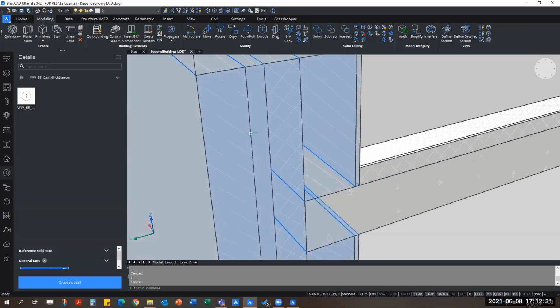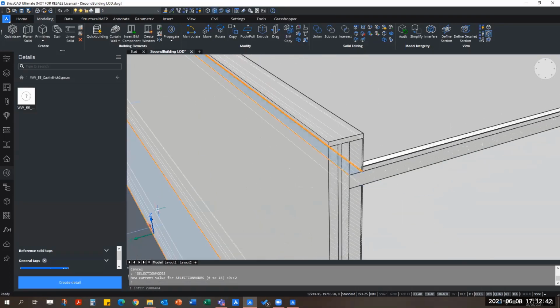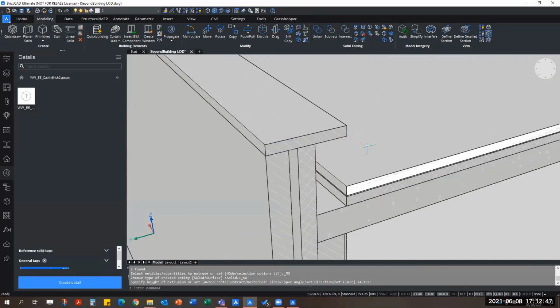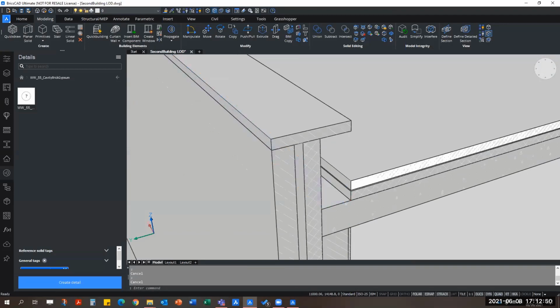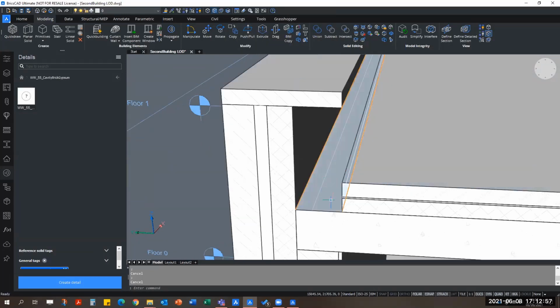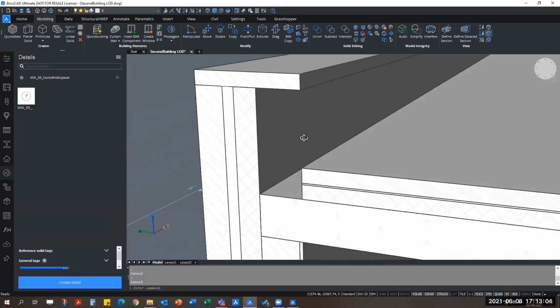few times you might not get it right as well. But normally what I will try and do is go on to select the faces and make sure I select that solid face. I'll hover around here and I'll do that. What I've done is select the solid face, and I've done an extrude rather than a push pull. In this case, what the extrude has done is subtract that volume out, which I clearly don't want. And I think this is fine.